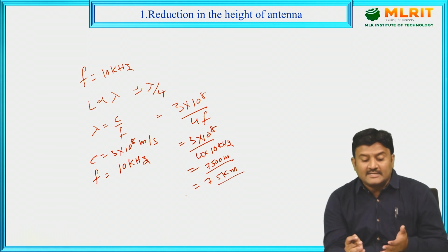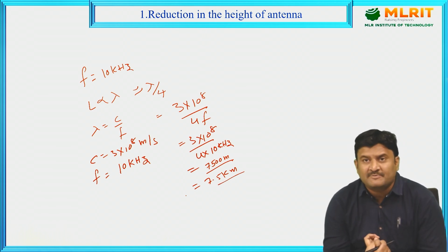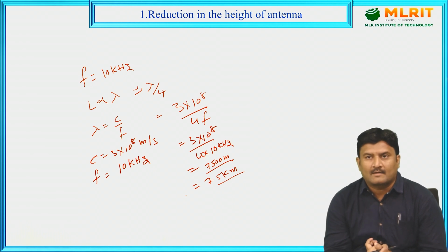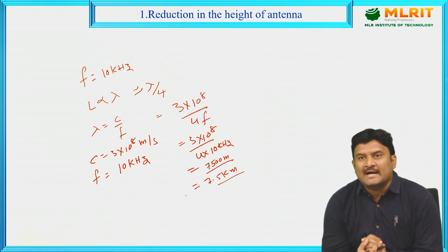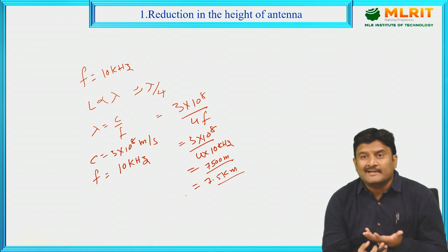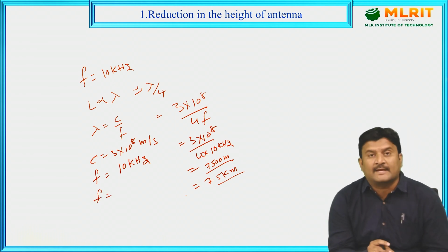Observe, is this much length of antenna practically possible? No. Therefore, you need to reduce the antenna height. Then automatically, what is the alternative? Definitely you need to increase the frequency.